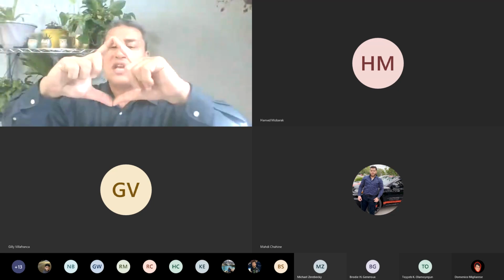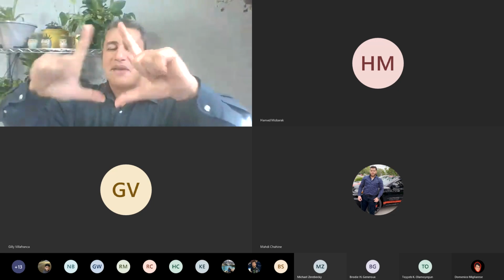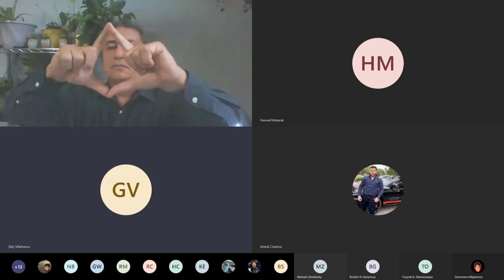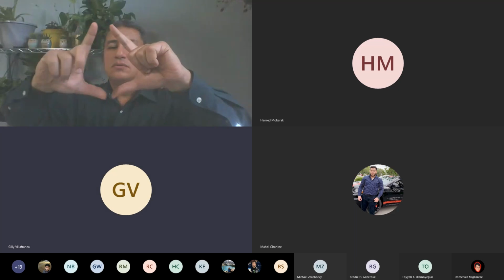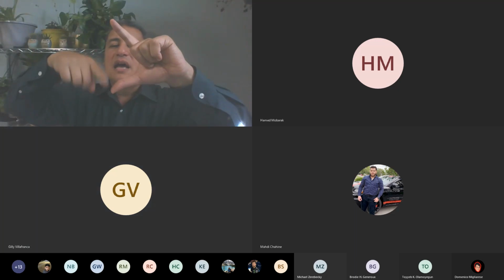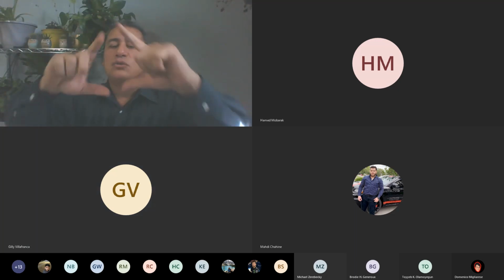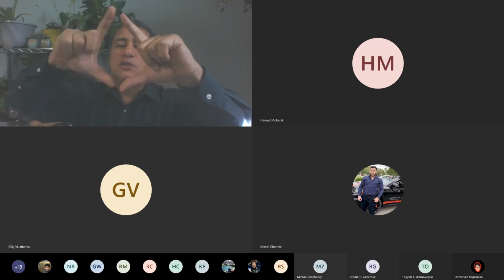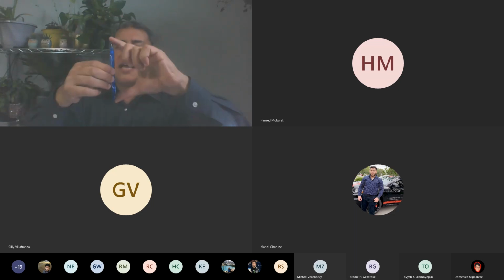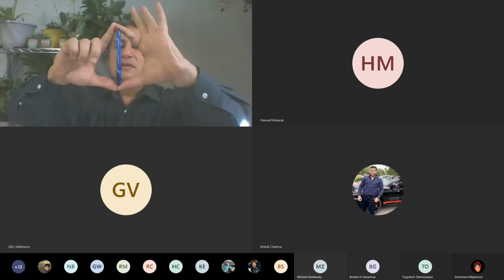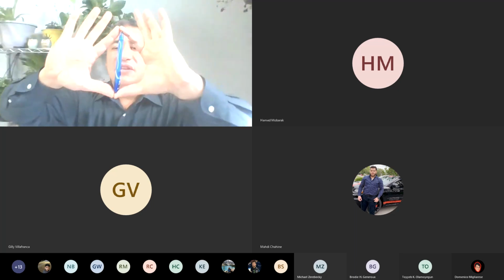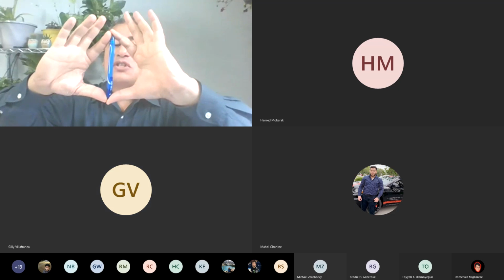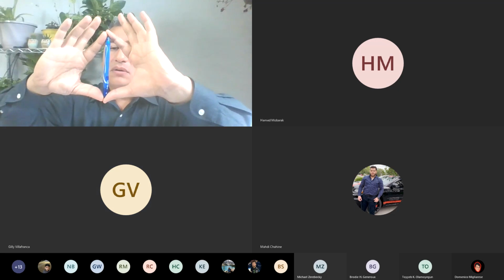What makes this system stable? How can I make this stable? You have to make it connection. No, you have to add a 5th member here that splits those into triangles. If you connect between those 2 points by, let's say, this, what happens in this case? The system becomes statically stable.